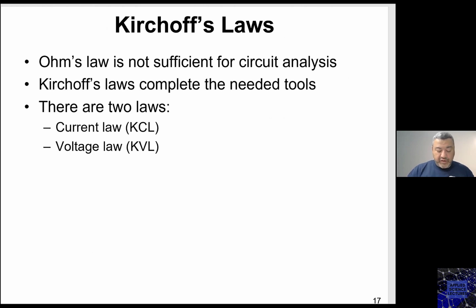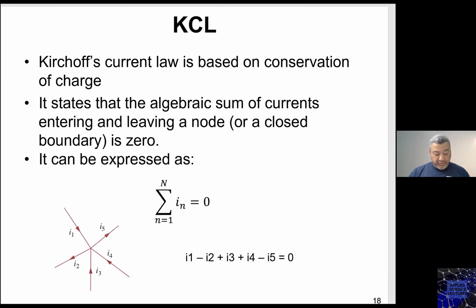So, Kirchhoff's laws. You have seen Kirchhoff's laws before in Physics 1010. We will reintroduce Kirchhoff's laws here in this lecture. One of them is voltage and the other one is current, and they are based on the conservation of energy. For the KCL, or Kirchhoff's current law, the law says that the summation of the currents entering and leaving a node is always zero.